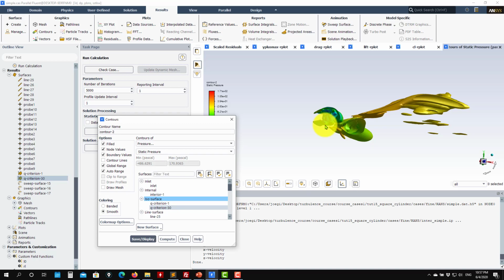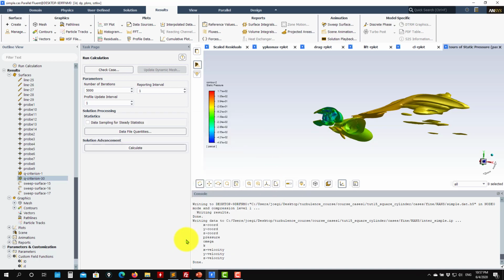So here, let's conclude something. The coarse mesh is a good one to get the initial condition, okay? But when we apply the criteria that we're using to assess the goodness of the mesh, it is not good enough. And then we have the fine mesh that is much better, okay? It can be better, but it's already much better. We see a big improvement, okay? So our next step, what we have here, we have the interpolation file for coarse and fine. Then we're going to move to the unsteady solver, the URANS. Then we're going to capture some time signals.